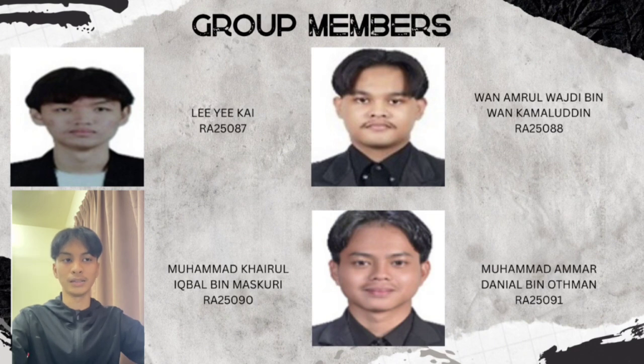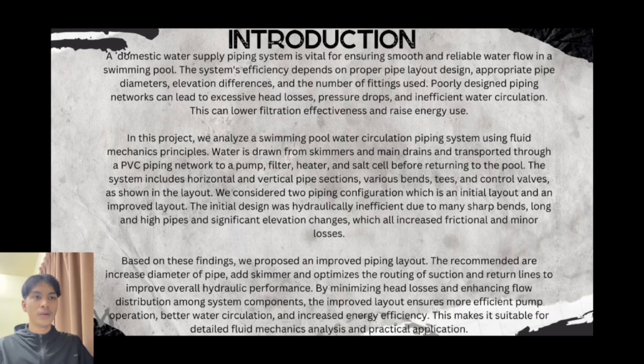Our introduction is a domestic water supply piping system designed for ensuring smooth and reliable water flow in a swimming pool. The system efficiency depends on proper pipe layout, design, appropriate pipe diameters, elevation difference, and the number of fittings used. Poorly designed piping networks can lead to excessive head loss, pressure drops, and inefficient water circulation. This can lower filtration effectiveness and raise energy use.